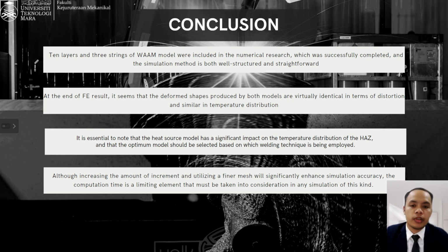Next, at the end of the FE result, it seems that the deformation produced by both simulations is virtually identical in terms of distortion and similar in temperature distribution. It is essential to note that the heat source model has a significant impact on the temperature distribution of the heat affected zone, and the optimal model should be selected based on which welding technique is being employed.